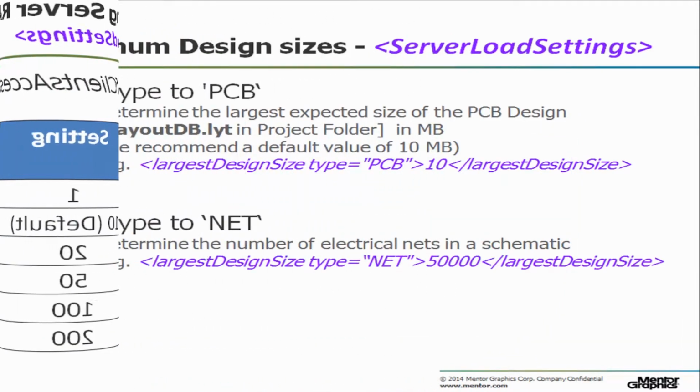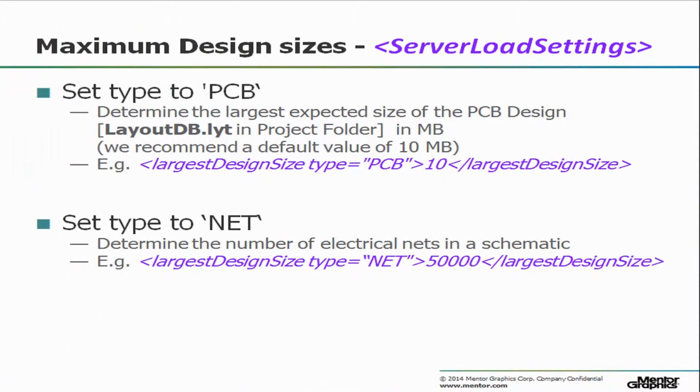The XDM server provides XDM Collaborate services to clients that enable viewing of designs and collaboratively reviewing them. To do that, it manages a database cache in order to improve the response time to clients. The size of the database cache is an important factor that influences the performance of the XDM server and requires configuration of the XDM server during the server deployment process. The configuration for you to influence the XDM Collaborate memory, and therefore the performance of the XDM server, is by setting the largest design size in the XDM server input XML file.